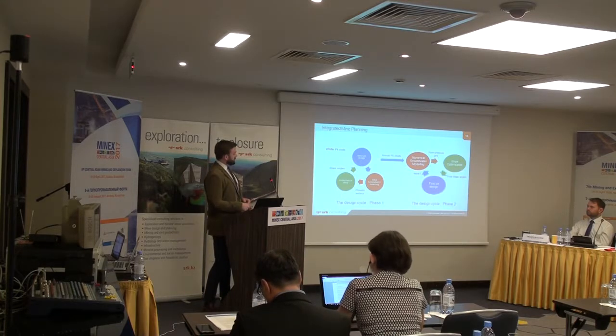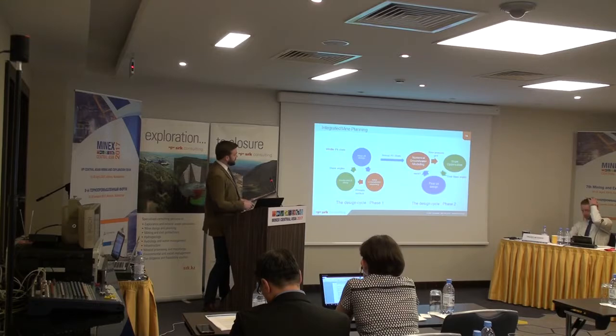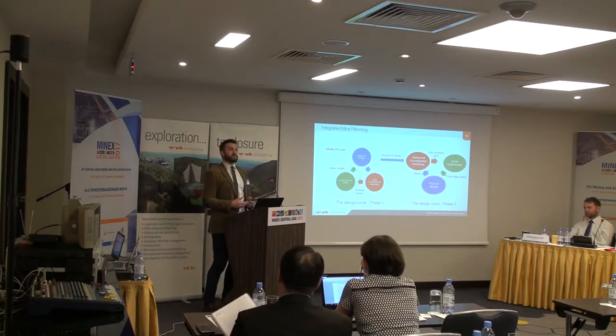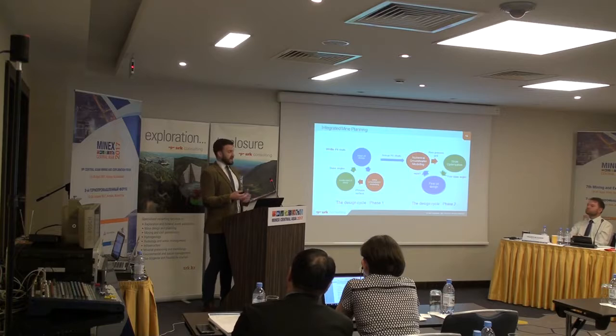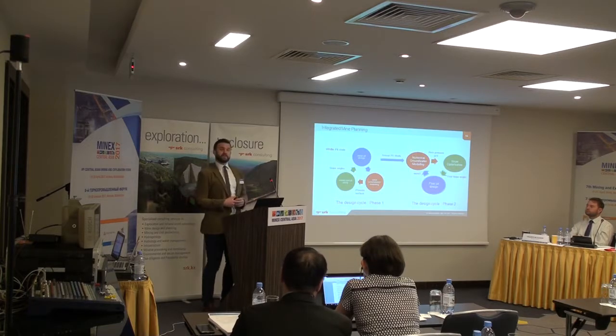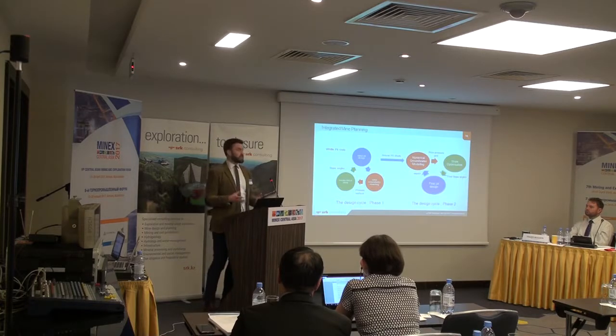From that, there will be a geotechnical and hydrogeological field investigation, and our hydrogeologists will carry out some initial groundwater modelling and try to understand what the current phreatic surface, or groundwater surface, is at the deposit. We will then import that into our slope stability analysis and try to work out what the slope angles are for this initial design phase, phase 1 we'll call it.